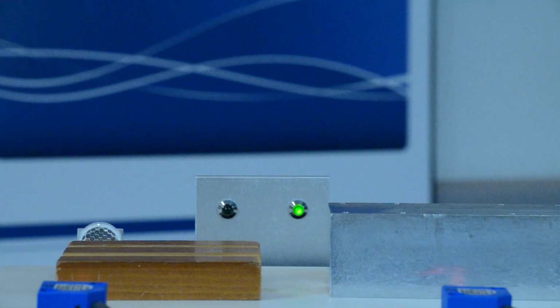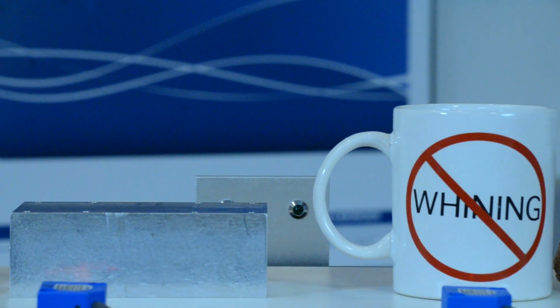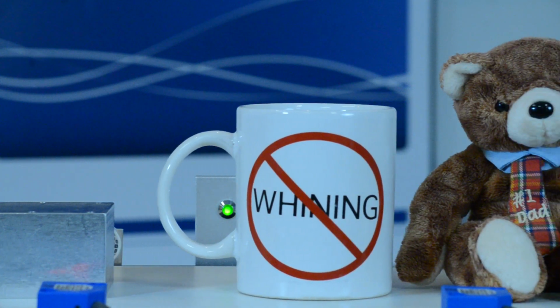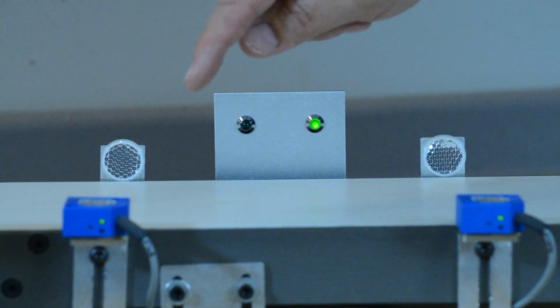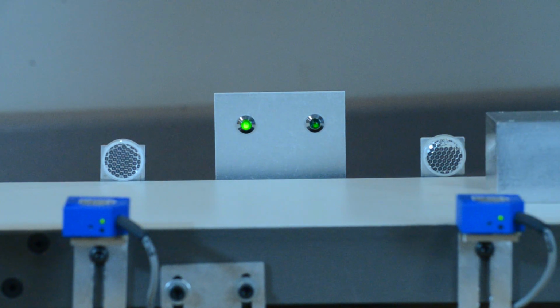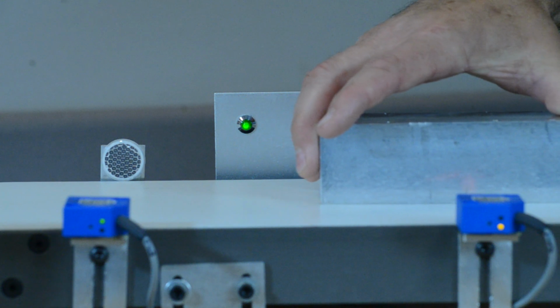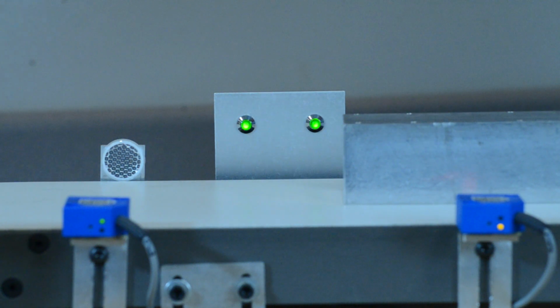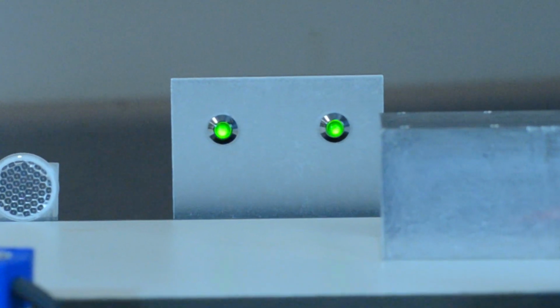Now we simulate a real-world situation. This conveyor has two sensors. The part passes the first sensor, triggering the timer for the interrupt. The second sensor will reset the interrupt as long as the part passes in the specified time. Otherwise, the timer will time out, and this will trip the interrupt program. In this case, it will stop the conveyor and flash the lights.